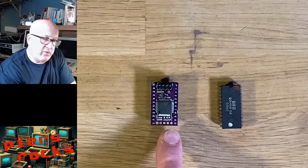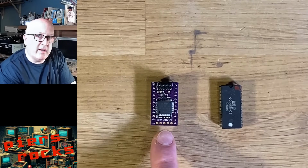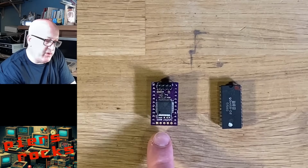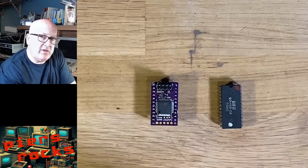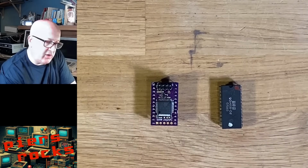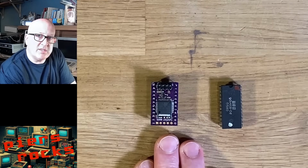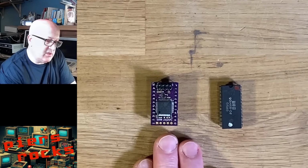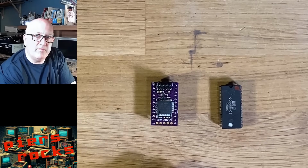There are 5 programming pins on the bottom here, and normally you only need to connect 3 or 4 of these pins to reprogram the device. And if you want to, you can reprogram it in the host, so you don't need to remove the chip, reprogram it and replace it. You can leave it in the host, leave the host turned on, and just reprogram this device in situ, which massively reduces the physical stresses on both this device and your host system.